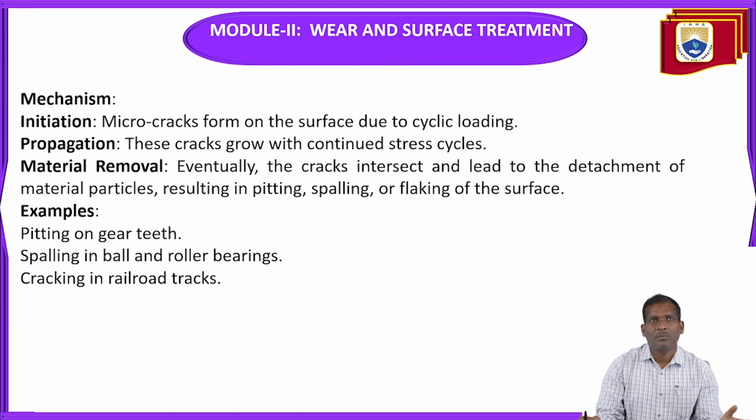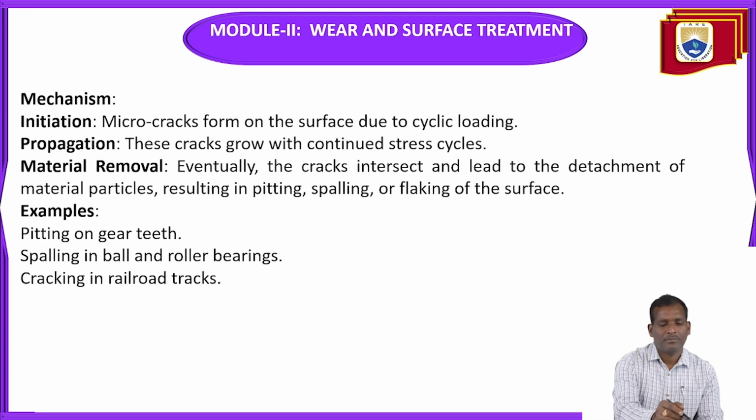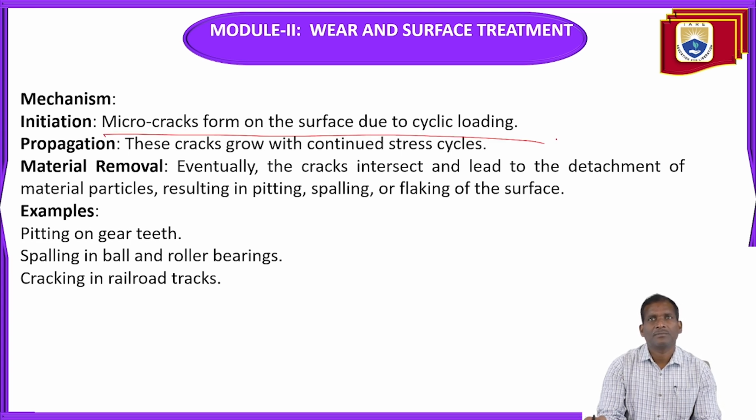So the mechanism behind this type of wear: initiation, where micro cracks form on the surface due to cyclic loading. Propagation, where these cracks grow with continued stress cycles.